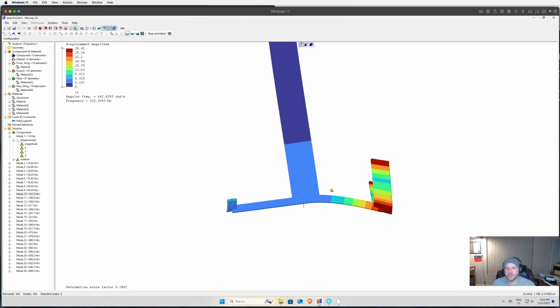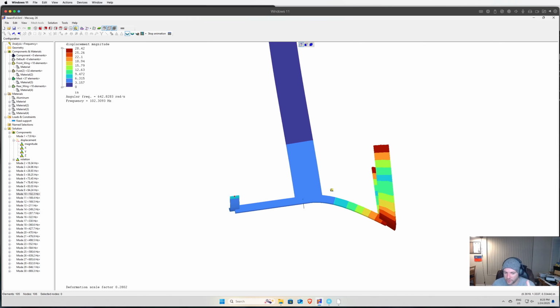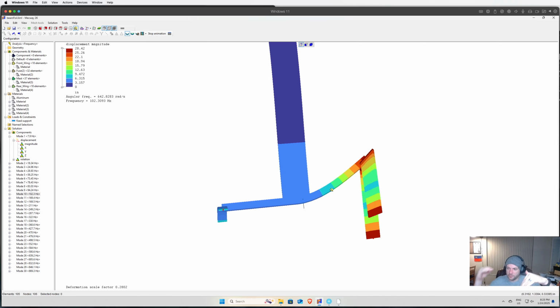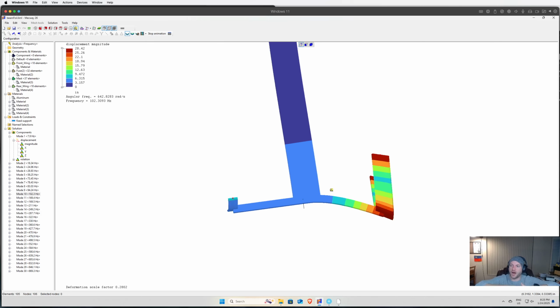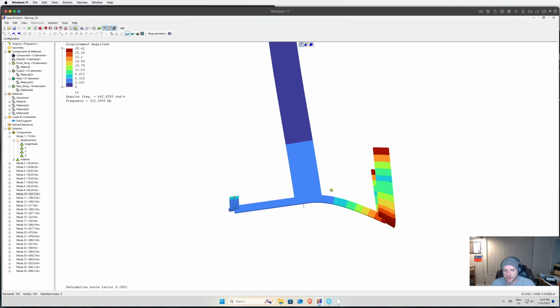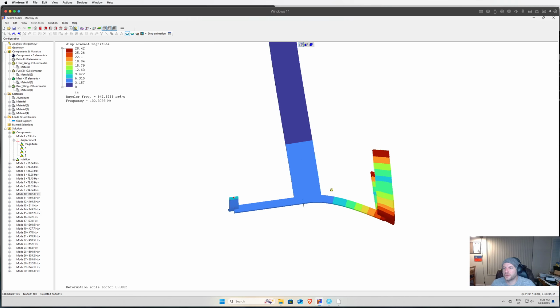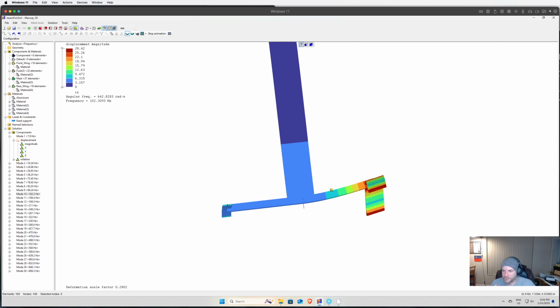But with this bending up and down, you're going to start getting this effect of the flow over this starts changing. So when it bends up, it's going to increase the angle of attack of that front wing and push it up further. Then it's going to snap back down, and then it's going to bend downward, and it's going to get this angle of attack pushing it opposite of lift. And what you get is this flutter situation, or an aeroelastic effect, where the deflections of your foil start interacting with the fluid, and it causes bad things to happen.